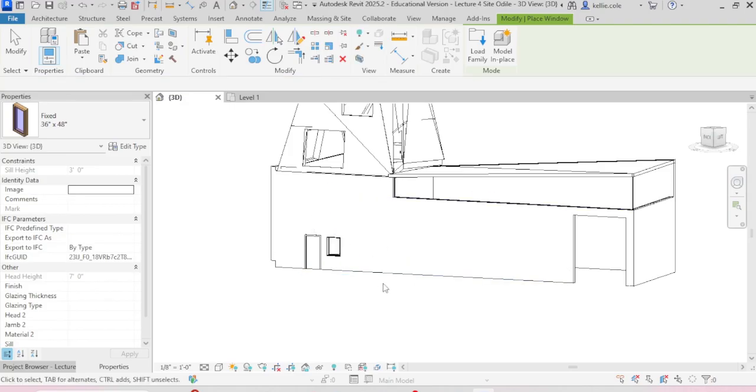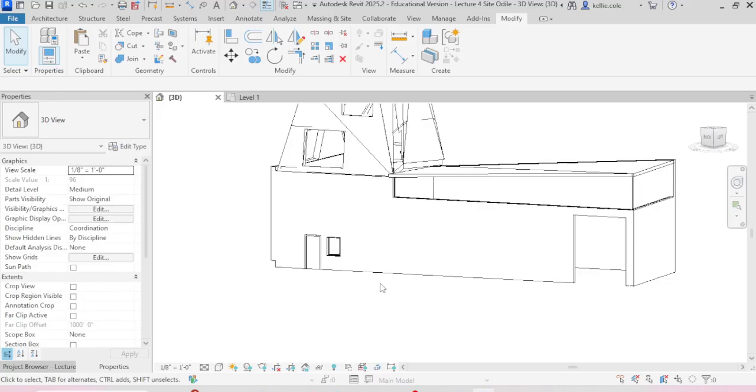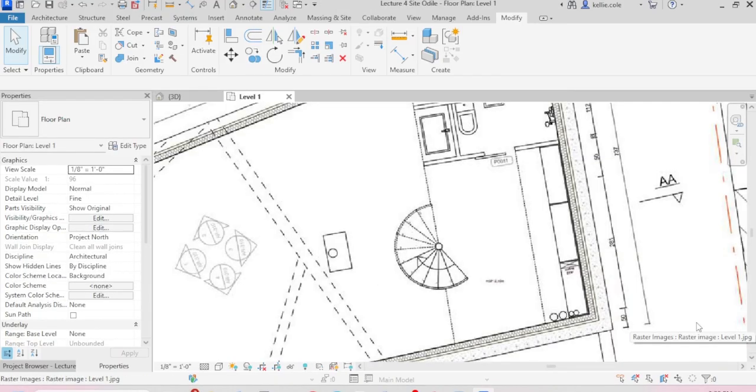And you can locate the window in the same way, locating and hovering over a wall to locate the window. So go ahead and do that on your own. We're going to locate a spiral staircase and go from just level 1 to the mezzanine to begin. Because every level is 10 feet in height, we can create one stair and then copy it up to level 5.